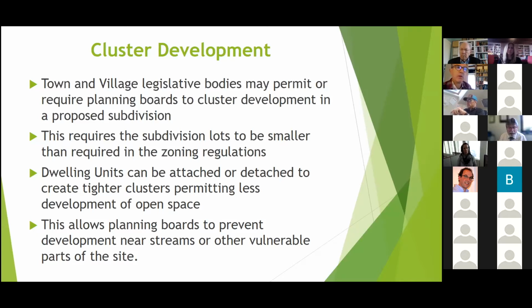So this is why in the model ordinance, our groundwater-based recommendation was, please consider the option of creating perhaps a series of littler clusters as opposed to one big cluster. Because if you have 5 or 6 houses in one node on a piece of property, you may be able to lay out individual wells and septics in an up gradient, down gradient relationship that will allow them to proceed as if they're individual, while also satisfying the cluster objectives of majority open space protection. So series of smaller clusters, uphill to downhill relationships, those are the groundwater guidance tools that one could use to get around the nightmare scenario that Tim wrestles with: underfunded HOAs that just can't make it work.